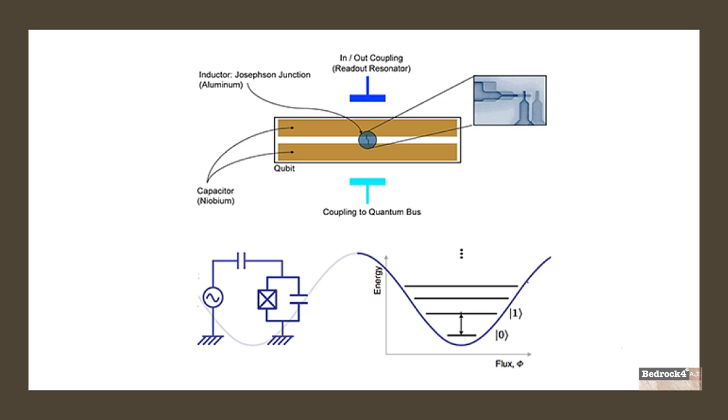It is made of a pair of superconducting aluminum electrodes that are separated by a very thin insulator that is 1,000th of a hair thick. Superconductivity is just a property of materials where materials exhibit zero resistance to electrons flowing in one direction when the material is cooled to a temperature below critical temperature. Aluminium, which is used here, has a critical temperature of 1.2 Kelvin. The superconducting state, achieved at near absolute zero temperatures, allows a resistance-free oscillation back and forth around the circuit loop.